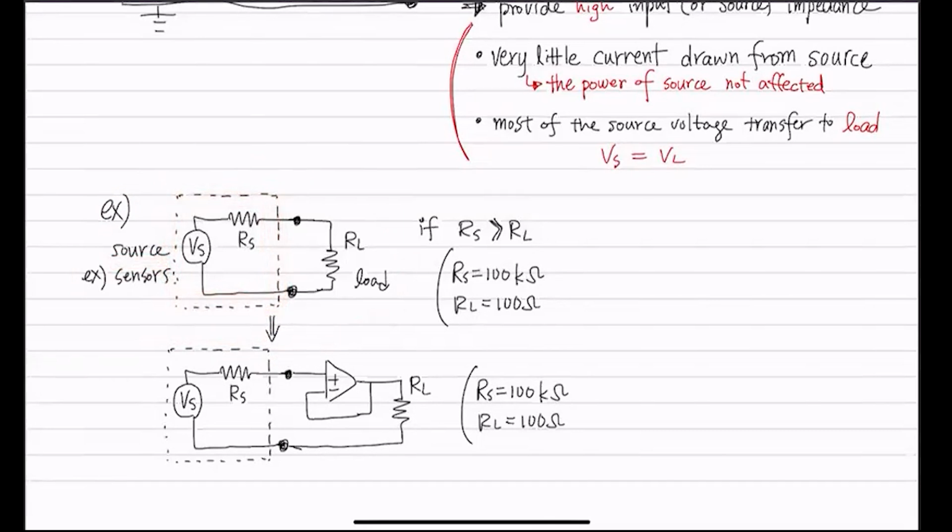Generally, a sensor generates some voltage, and we are measuring voltage. It's going to have a small voltage source and some parasitic resistance in there. And in order to measure voltage, you need to have a resistor, that way the current flows across it and then you can measure the voltage. So you have a low resistance load like that.